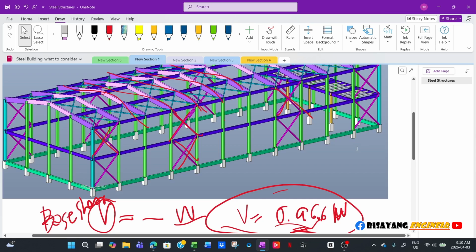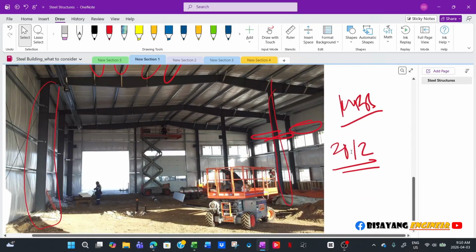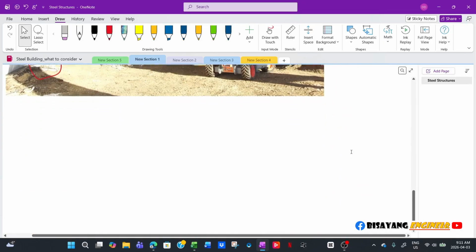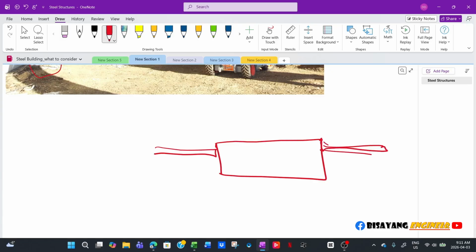But if there's a dynamic involved, like moving equipment, rotary or whatever, for example a generator, it will vibrate. Then the best option, or what we usually do, is we will have, if this is a slab, a separate foundation for the equipment, and then we will provide a gap here, normally half an inch, and then we will provide a sealant.